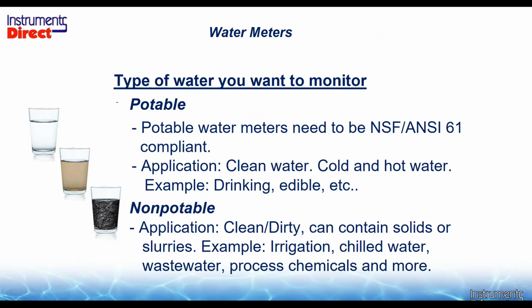Non-potable water is the application of things you don't want to drink. So if there's dirty, contaminated water that has suspended solids, not necessarily filthy dirty, there could be other applications like irrigation. The water that you're irrigating your field with is not required to use an NSF certified flow meter. Why buy a more expensive flow meter when it's not a potable water application? Inside the facility, you're monitoring chilled water and hydronic loops, and on the process side maybe your water and wastewater treatment plant and other process chemicals and more.